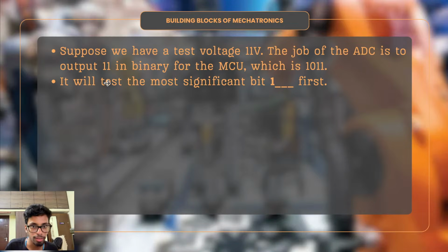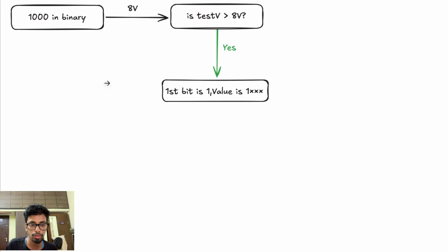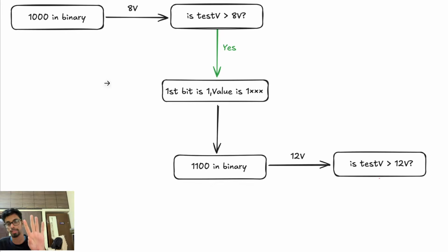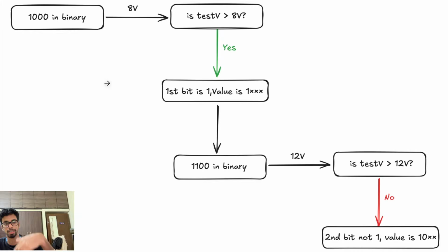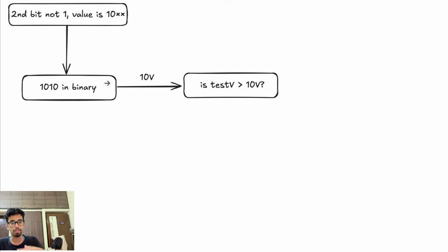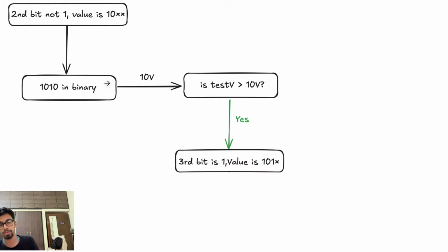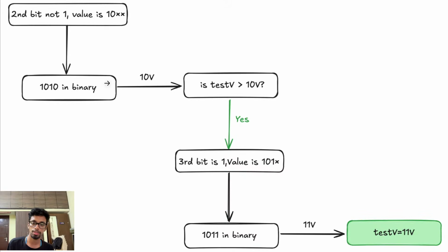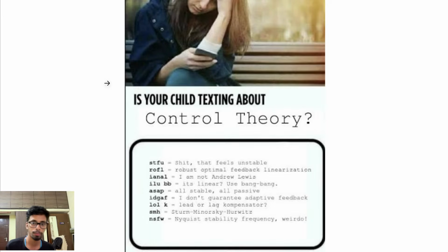I think that is it. The 4-bit encoder was able to solve the problem in 4 steps rather than looping through the entire set of integers 0 to 15 exactly once and doing 16 steps. So instead of 16 steps, it has found the voltage in 4 steps. So it's pretty efficient by using binary.